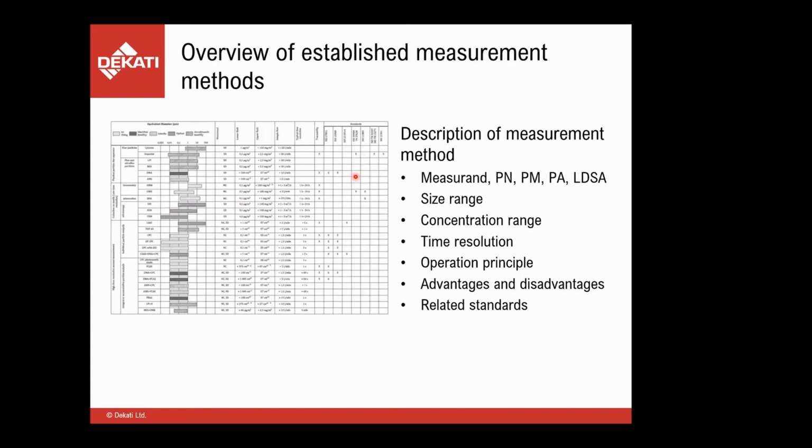So as said already, it has a wide range of different methods for the measurement of aerosols, with many different measurements: particle number, particle mass, particle surface area, and the lung deposited surface area as examples. Different methods have different size and concentration ranges, as well as time resolutions.